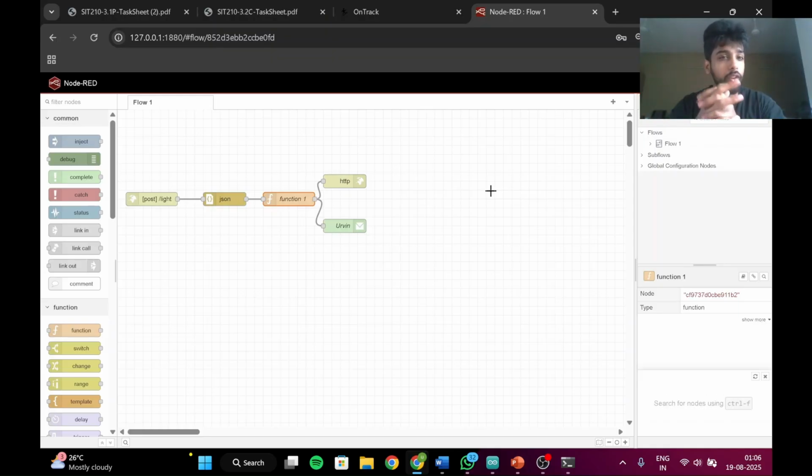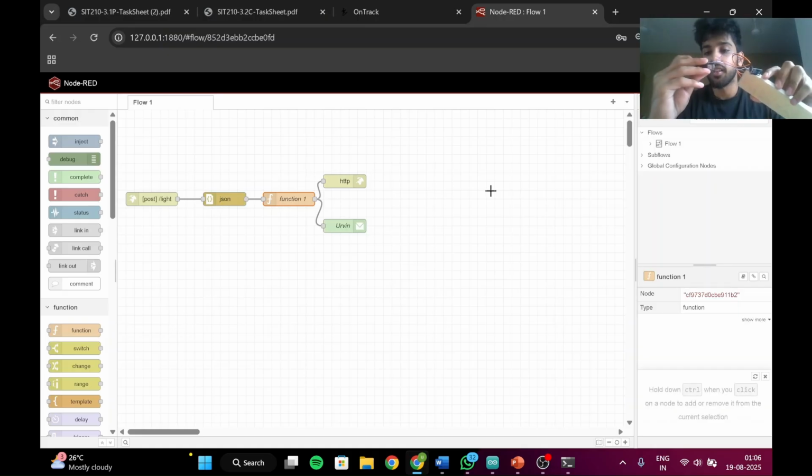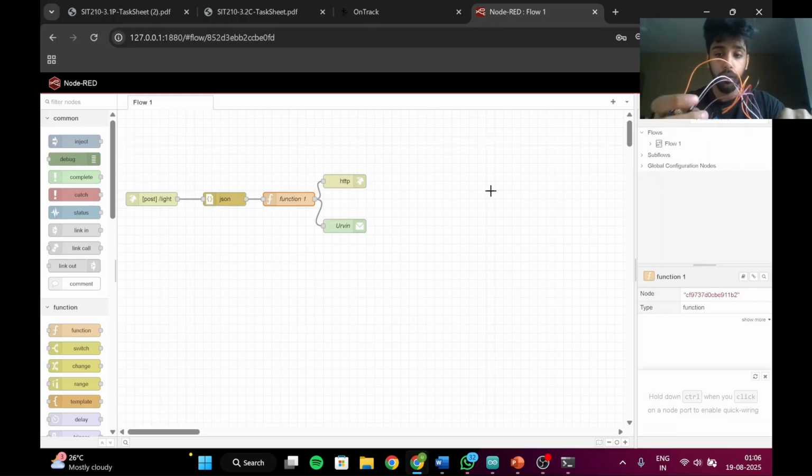Because I have discussed all the main points, I would also like to tell you how to do the sensor integration part. You can see we will connect our Arduino and the ambient light sensor over here. The SDA and SCL are defined on A4 and A5, and then we will give the common grounds here, and then I'll connect the VCC of the